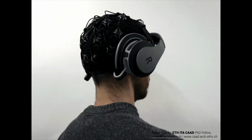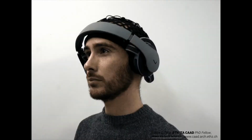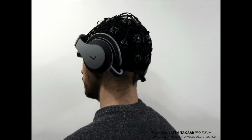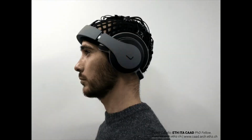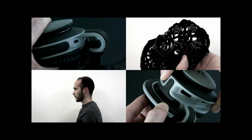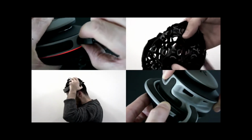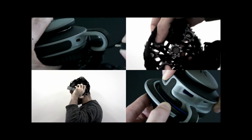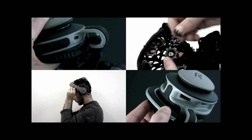So it is mostly using open BCI boards, sampling at 125 Hertz, with 16 channels only, and mounted on a custom headset, as you can see here, and including LiPo batteries and more practical electrode placement net to ease the experiment.